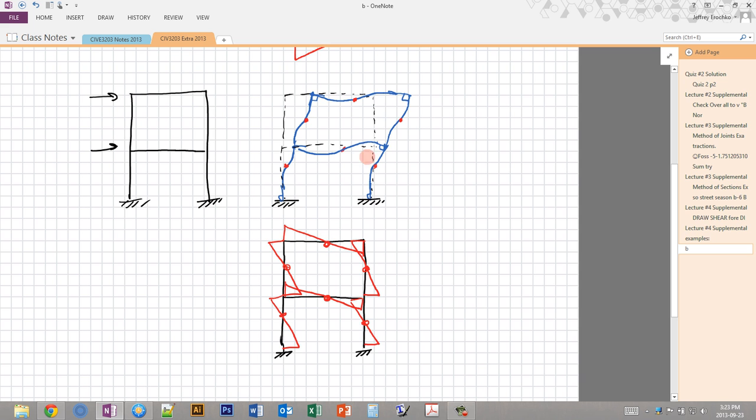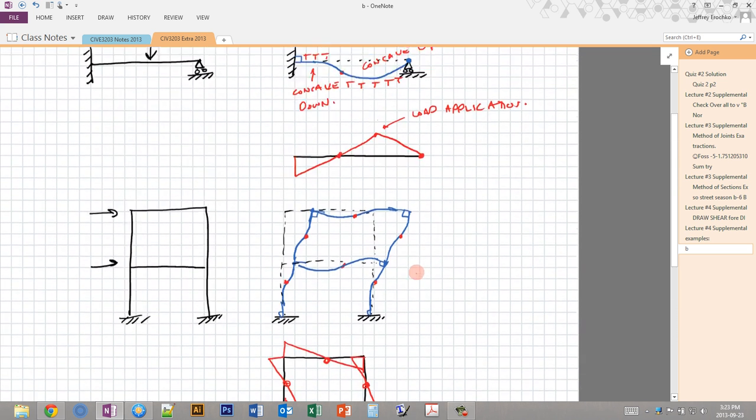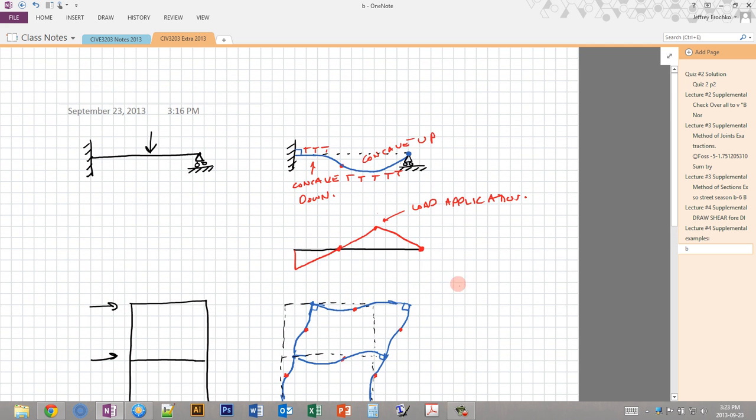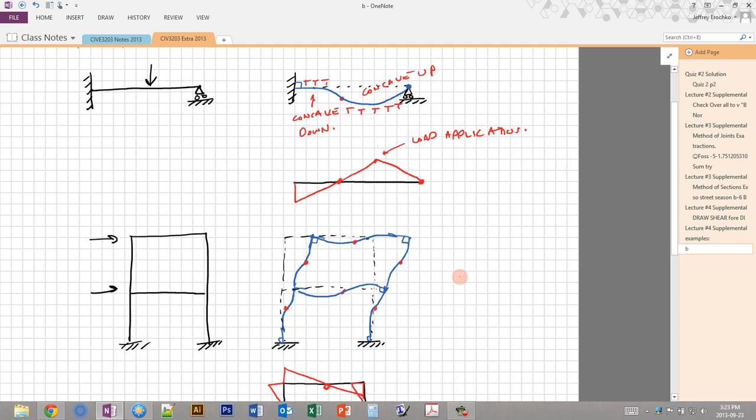Points of 0 moment give the points of inflection, and the other rules still count, like the fixed ends and the corners having 90 degrees, and then that way you can calculate the displaced shapes based on the moment diagrams. And that's what generally you'd be expected to do when you do a bending moment diagram question. But good news is that that is easier than this process.